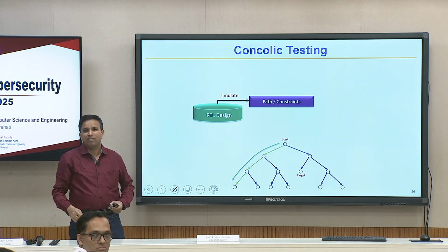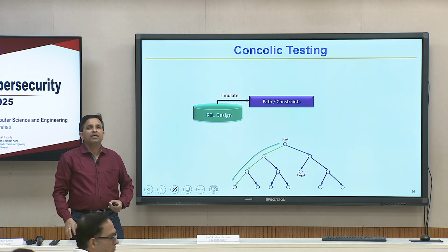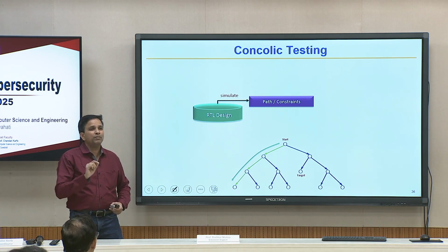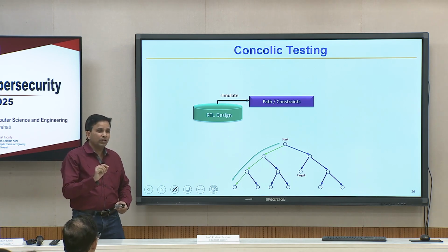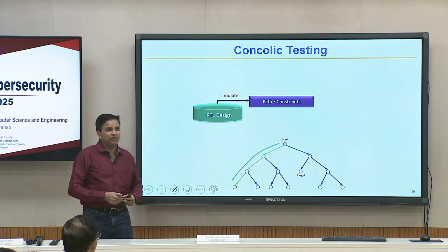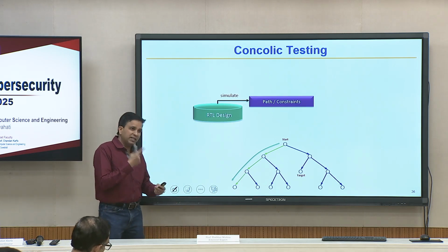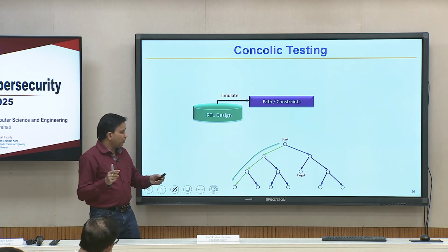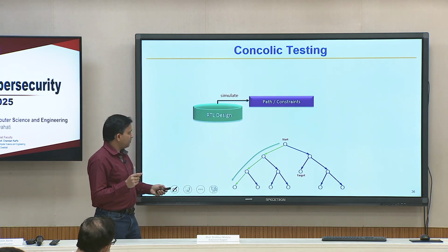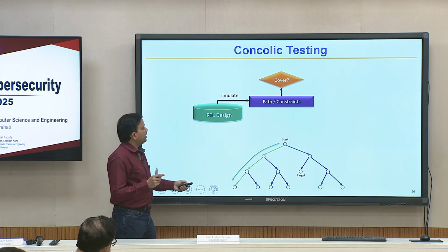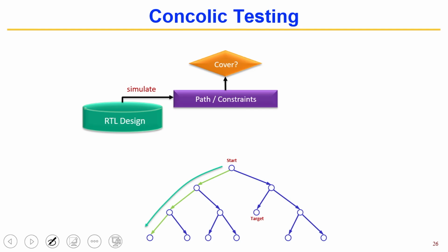Because the assertion could also be false. The assertion condition I might not have written correctly, so it can fail at the wrong time. So I want to make sure that the assertion I wrote fails correctly when it is supposed to, that it is a valid assertion. During design time itself I have to generate a test and check my assertion, so that at run time there is no more false positive, false negative story. Thank you.